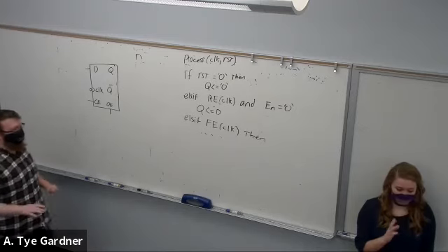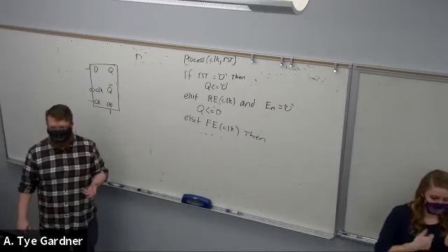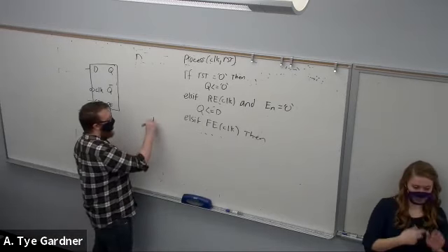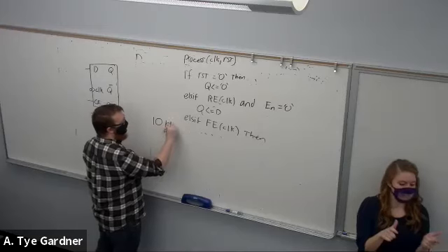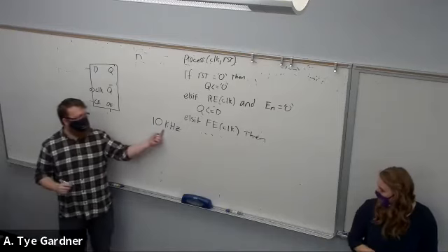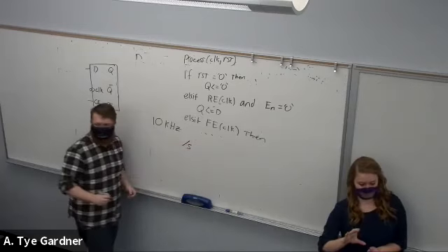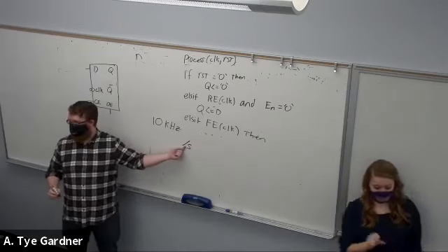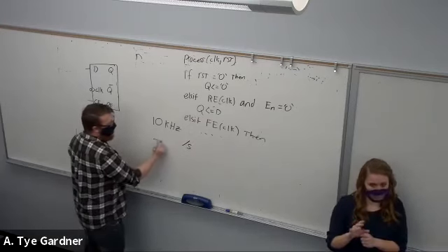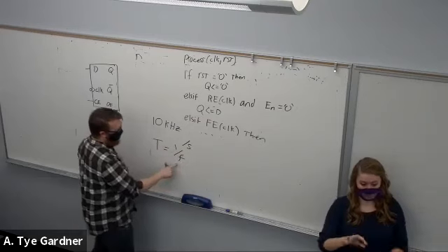It's fine. We'll start off next with an application of the flip-flops, which is what we call clock division. The clocks that we use are going to be labeled with a speed, something like 10 kilohertz. That means 10,000 times, and hertz is a unit of per second. So that's 10,000 per second. That relates to time in seconds by T, the period, equals 1 divided by f, the frequency.